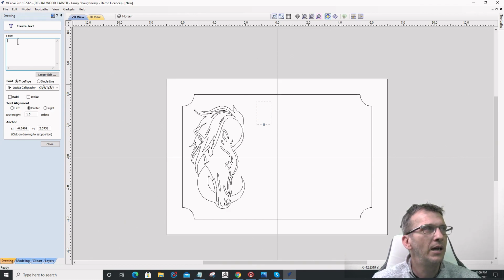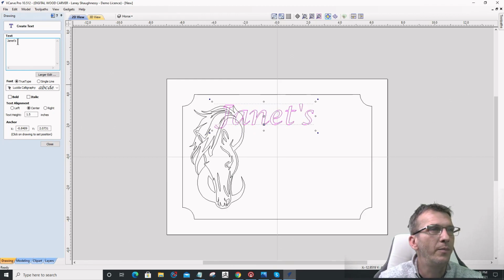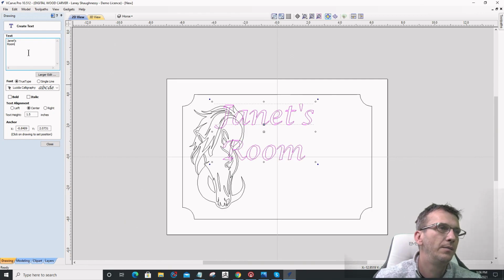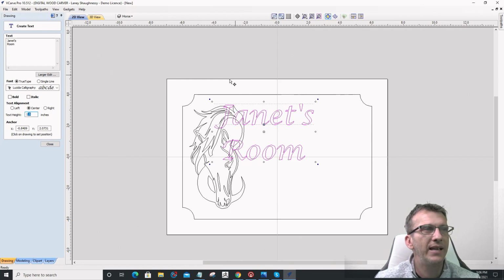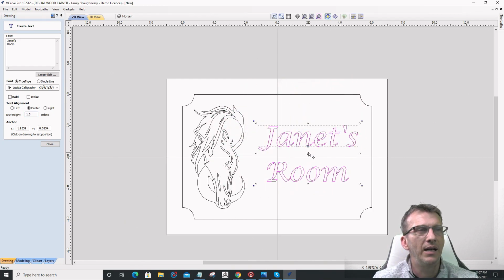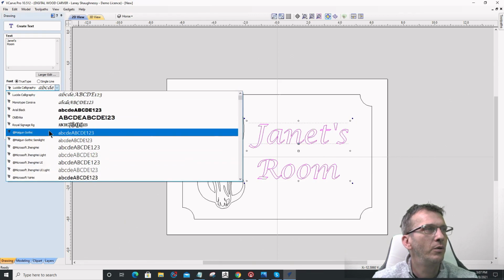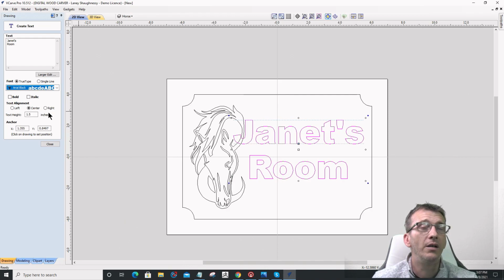So over here I'm going to type in Janet's with apostrophe S and hit the enter key and type in ROOM. All right. And then I can set my text height if I want. Now, you see how my text went over the horse? That's not critical right now because I can move it around. I'm not going to do its final positioning until I get all the text written and everything. But now I want to cycle through and determine what font I want to use.